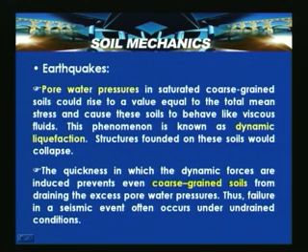We have learned that whenever the total stress equals the pore water pressure, the soil loses its shear strength, because effective stress is 0. So this phenomenon is known as dynamic liquefaction. So structures founded on these soils would collapse.